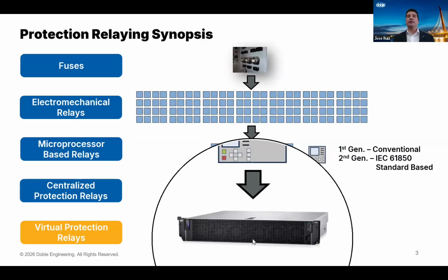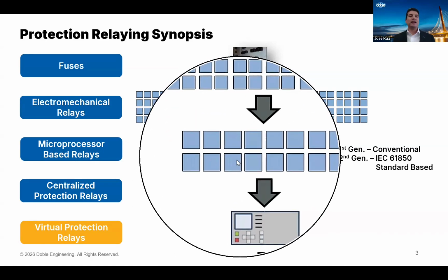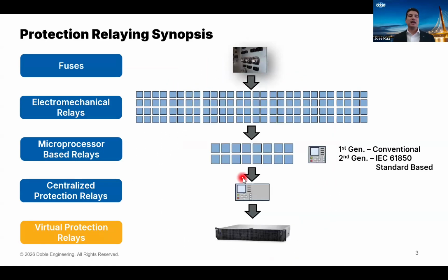Maybe you have heard the word data center in the IT space, and that's true because the IT world has been using servers for many, many years. But it's something relatively new to the power industry, because we are used to electromechanical relays, microprocessor-based relays, and maybe some of the companies get into a centralized protection approach with a microprocessor-based relay, but now we are looking at virtual protection relays, which basically reside in a computer server.